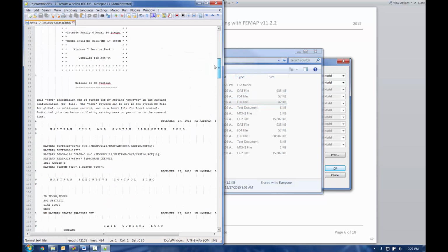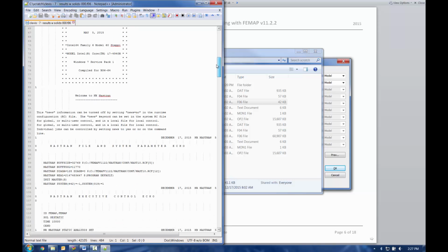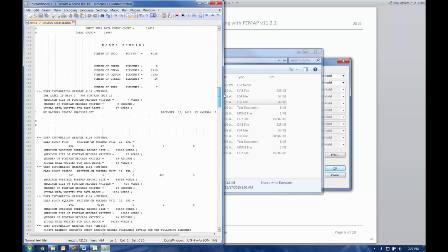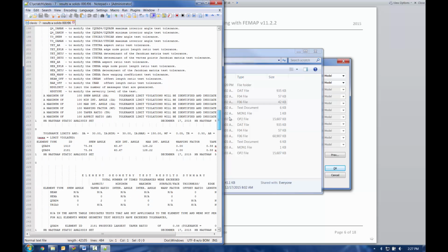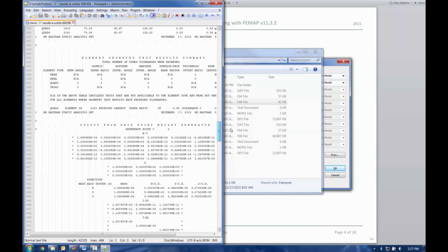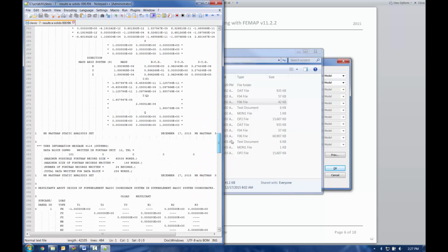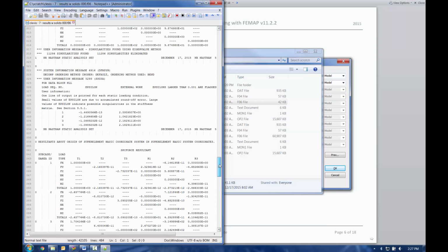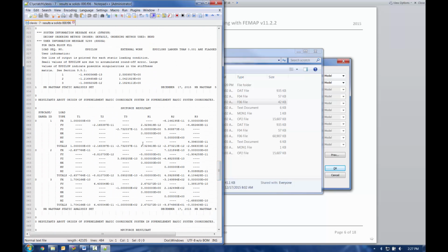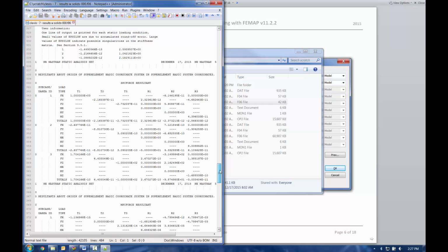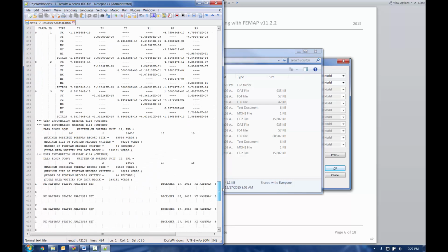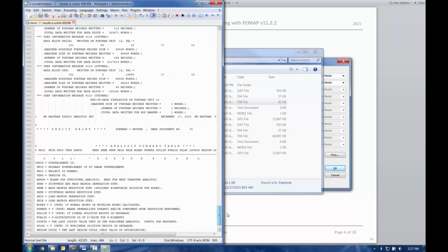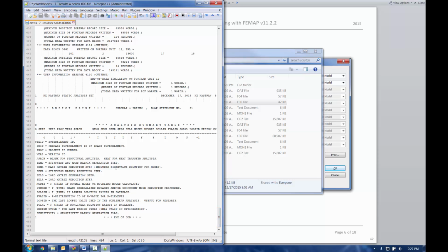This one is fairly short, a little information about the solver, some good information for the analyst to check in here, I would say, is the O load, get your total input load to your model, and your SPC force resultant, how much reaction force your constraints are seeing. But once you scroll down, if there's no errors in your analysis, that's all you get.